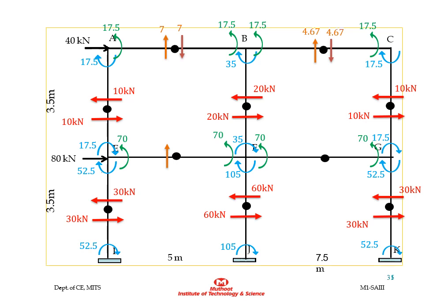So in the top floor, the beam shear will be 17.5 divided by 2.5, that is 7, acting in the upward direction. Then just to the right of the point of contraflexure, the 7 kilonewton beam shear is acting in the downward direction.